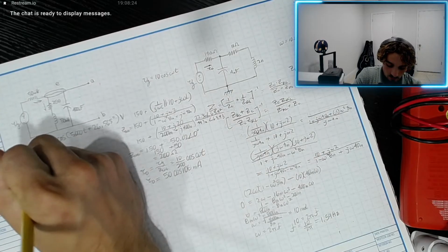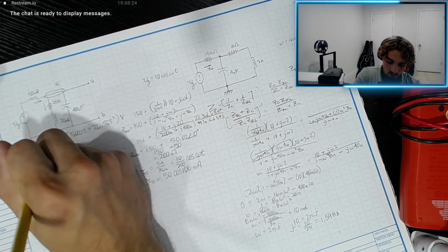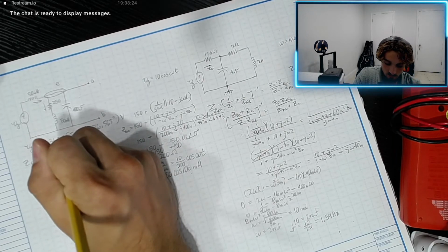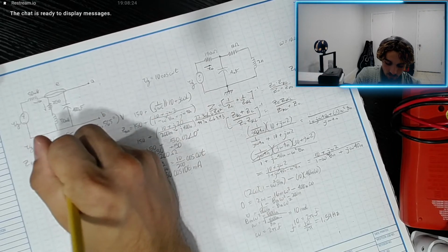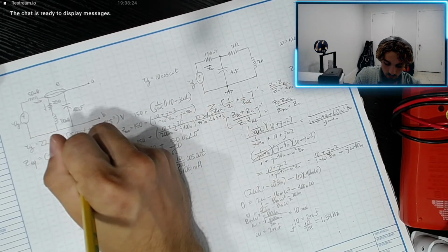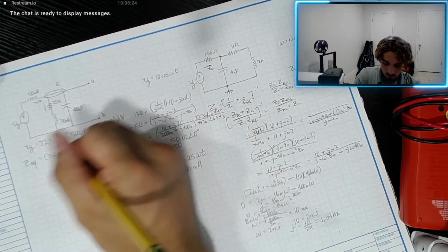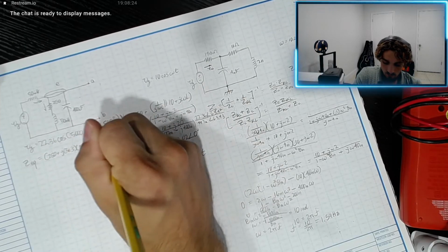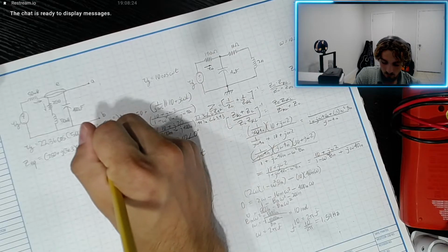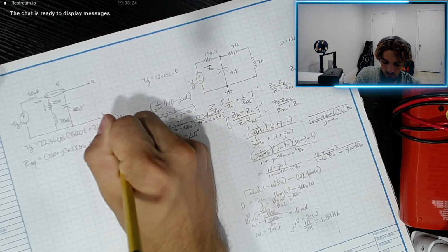We want to find the total impedance, Z total, or rather just Z equivalent for the parallel, equals 250 plus j omega, 5,000, times 50e negative 3, in parallel with negative j over omega, 5e3, multiplied by the capacitance of 400e to the negative 9.